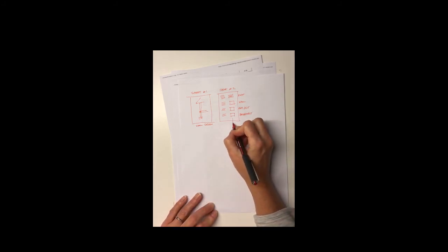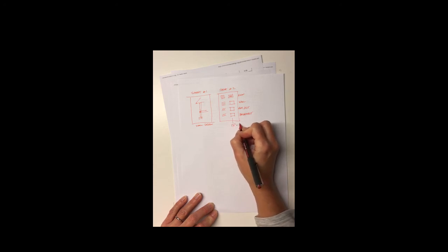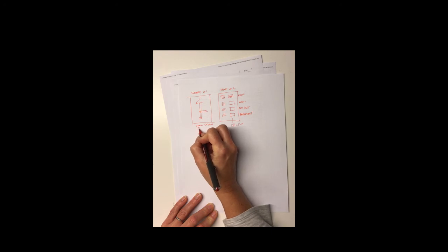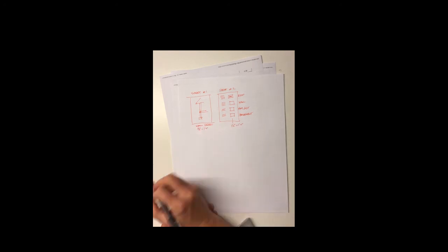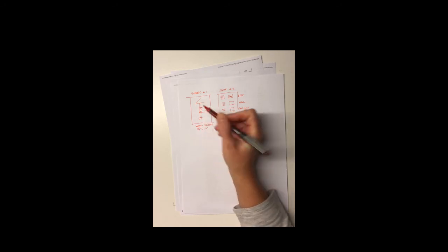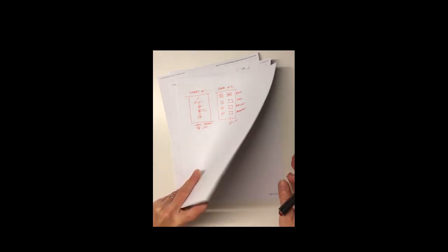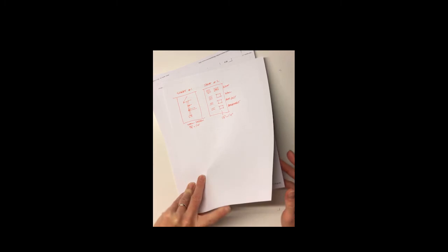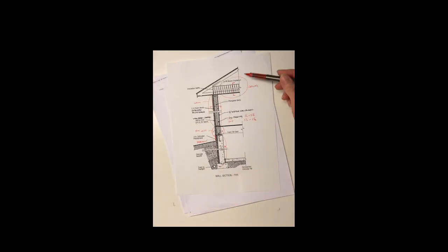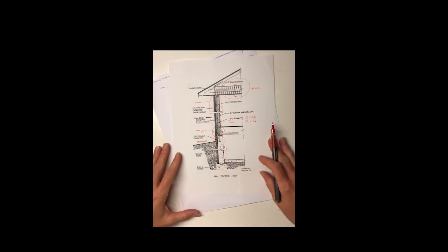And for those details, I would say roughly 1.5 inches is equal to 1 foot. For the wall section, 3/4 of an inch is equal to 1 foot in terms of scale. Those are at least typical scales for drawings of this. You can always use break lines if you need to break up those long distances, similar to what I am showing you here in this wall section, where you have all of those pieces. Sometimes those break lines are there to allow it to be drawn to scale but still fit on a sheet.